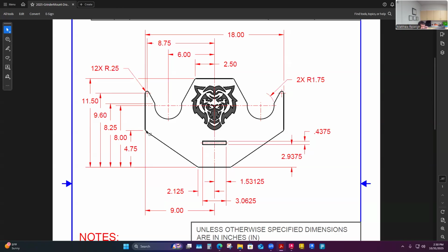Essentially, it's like a fillet radius, and it's common practice in finished parts where I don't want a sharp point if it's something I'm going to handle. I would leave sharp points mostly if I'm creating welding geometry, like weld joints, and I'm speaking to welders here, so I know you're thinking, I don't radius all my corners when I'm building stuff. I like nice sharp corners, edge to edge fit-ups. So a lot of actual parts that get cut and become part of an assembly are going to keep sharp corners, unless it's some finish work to the inside here or something.